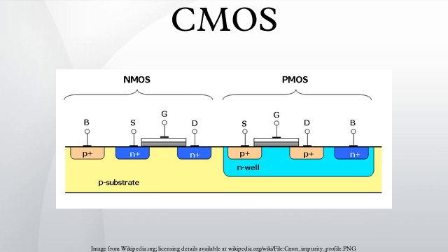Inversion. CMOS circuits are constructed in such a way that all PMOS transistors must have either an input from the voltage source or from another PMOS transistor. Similarly, all NMOS transistors must have either an input from ground or from another NMOS transistor. The composition of a PMOS transistor creates low resistance between its source and drain contacts when a low gate voltage is applied and high resistance when a high gate voltage is applied. On the other hand, the composition of an NMOS transistor creates high resistance between source and drain when a low gate voltage is applied and low resistance when a high gate voltage is applied.